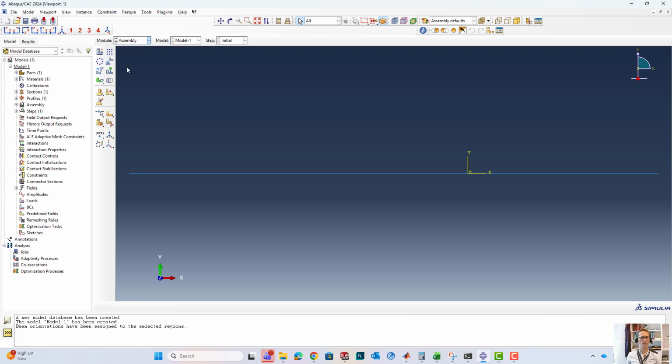I'm essentially working through this series of steps here to build my model, and this is the process of building a finite element model. Define a part, create a property, build an assembly, create a step. I can then do interactions, so if there are multiple parts there can be contact, I can apply loads. In a frequency analysis there are no loads normally, it's like a free vibration problem. I can then assign a mesh, and ultimately I can create a job and submit it to the solver.